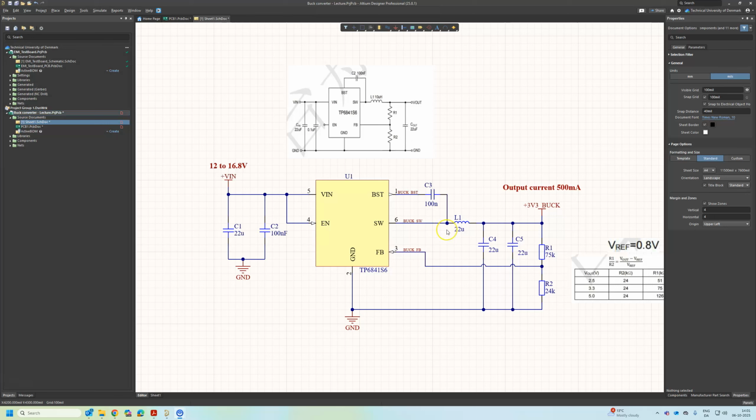You can design your LDO or your buck converter for a specific application. When you do that, values such as the inductor value, for example, will change, and other calculations will change too. It doesn't mean that with a load current of 800 milliamp this will not work. It will work, but if you make your calculation according to 500 milliamp and this input, the performance will be different if you're using 800.